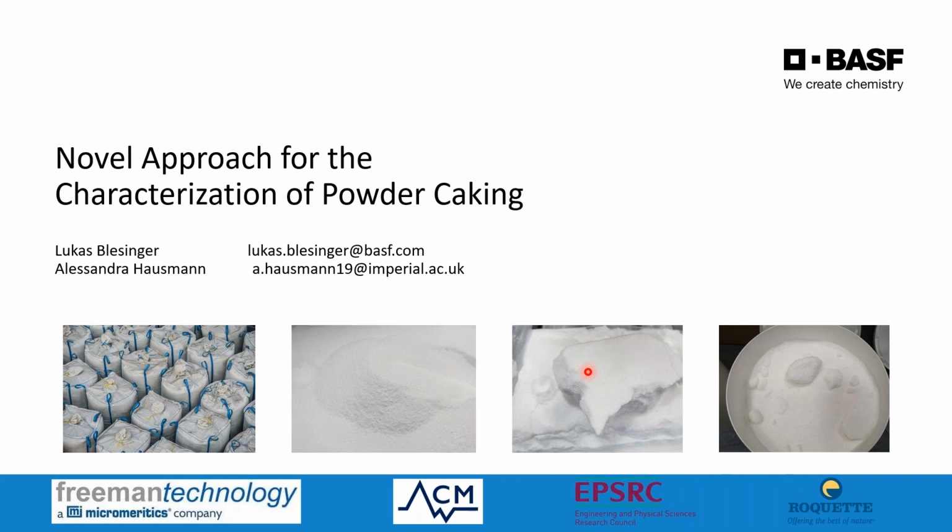Someone asked a question earlier today, why does caking occur? There are 3 or 4 mechanisms by which caking occurs, but I'll give you some of them just to help. If a crystalline solid adsorbs a lot of water, then actually you can dissolve the surface of the particle in question. And then later on, when that particle dries out, you get a solid crystalline bridge form amongst the powder bed. That is one reason you can get caking.